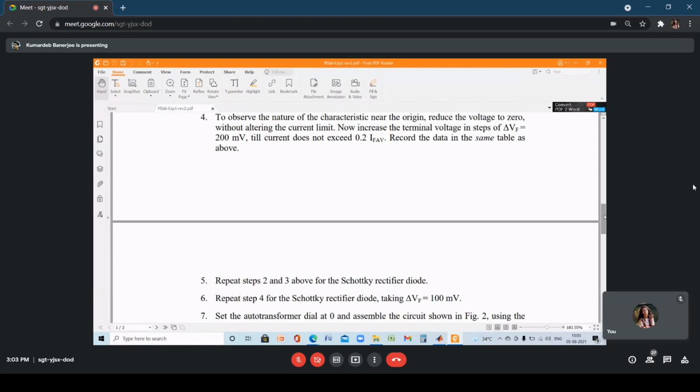So if you impress a voltage of 0.8 volt across the diode, the current will clamp to 1 ampere. Because anything beyond its cut-in voltage means the diode becomes almost a short circuit. So a huge amount of current would flow through the diode, but because there is a current clamping mechanism, the maximum current that flows through the diode is 1 ampere.